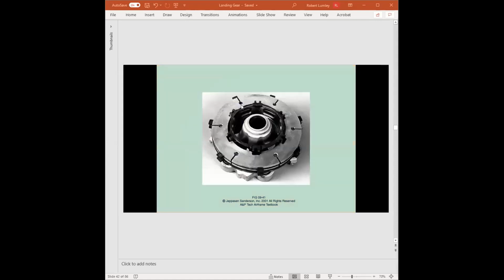Okay. Here we have this one. If you notice, this is the stator of a multiple disc brake system. And as I said, in the multiple disc brake, the stator can float, but it can't rotate. What holds it from rotating is this device here, which is called the torque tube. You can see the protrusions coming off of the torque tube that fit into the little notches of the stator. Now many times I ask this question: if you see in the stator, notice that there's a slot with a hole, a cut in it with a hole.